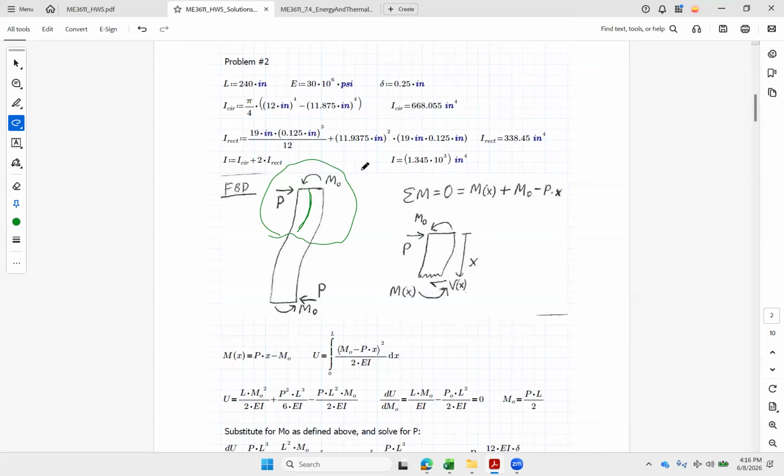Right? And the whole free body would tell me that whatever force I'm pushing with on the right has got to also be the same there on the bottom. And I've got anti-symmetry there. So however much curvature is at the top, I'm going to have the same curvature with the smiley going the other way at the bottom. So I'm also going to have a moment down there. And I just need to pick one end or the other. Once I find these two, I'll know what the bottom ones are as well. All right. So let's take a little slice from the top. I'll put X from the top as well for convenience.